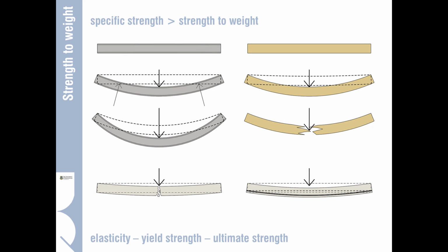However, we don't use steel in such large quantities, and the property of steel is that it's got a very impressive strength to weight ratio. We can get long spans and the material is very stiff. Its ability to resist deflection is much greater than timber and unreinforced concrete and also reinforced concrete.